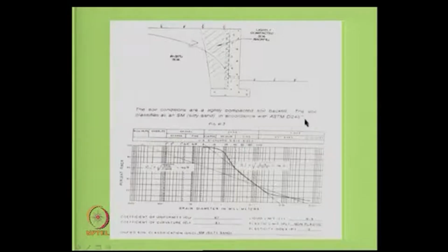So, the soil conditions say that the soil is lightly compacted, because particularly as I said, close to the retaining wall, in the RE wall or any of these things, particularly in RE walls, we do not have high compaction because it will affect the panel. In this case, yes, good compaction is all right, but normally we do not do that because you only have a drainage material here. Because of the compaction, it should not get powdered, or the drainage pocket should not get closed. So, again we have done that same analysis.